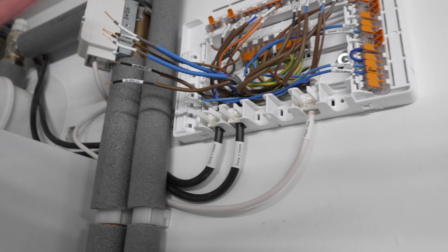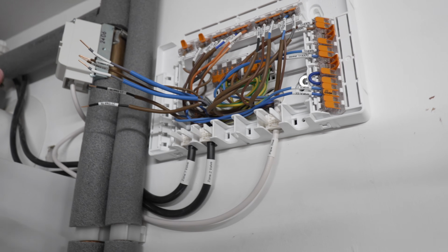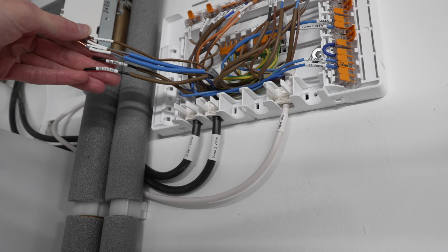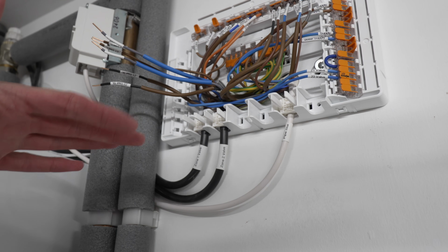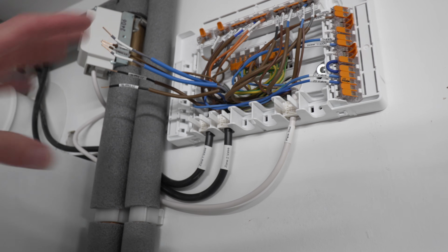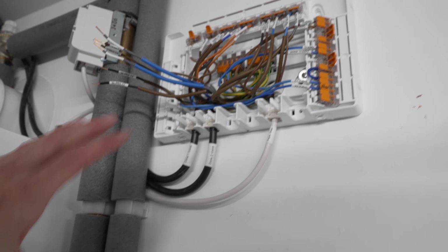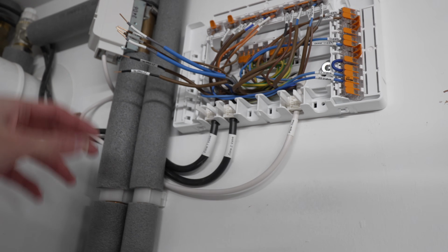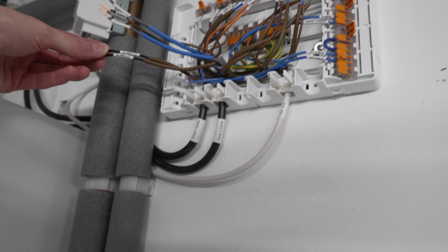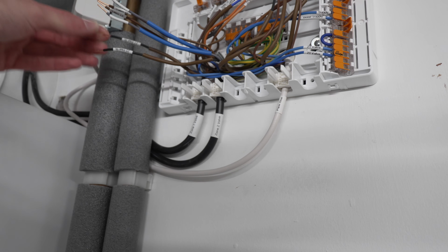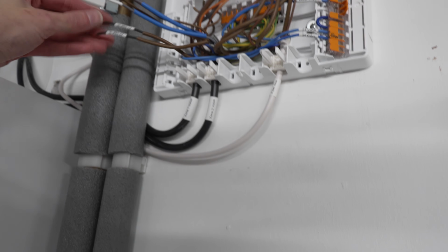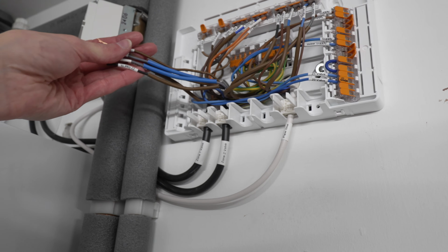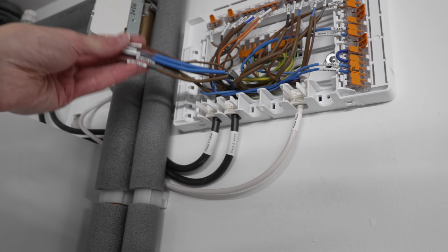Now, you could obviously just cut these off, get rid of them. I'm not going to do that, and I wouldn't recommend you do it either, just because there's always a chance in the future you might want to repurpose these. You might want to go back to wired thermostats, or while with the Wiser system, the wireless thermostats can only be battery powered. If you, let's say in the future, switch to a system like Nest, with Nest you can use these thermostat wires to pass a sort of DC, I think 12 volts or something, from your Nest receiver to the thermostat, so at least the thermostat doesn't need batteries. So I'd recommend leaving these wires in place just in case you ever want to use them in the future.